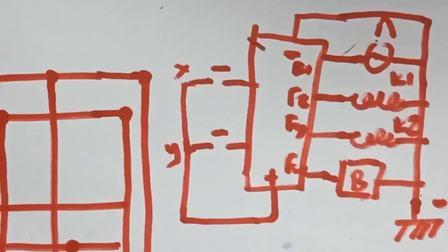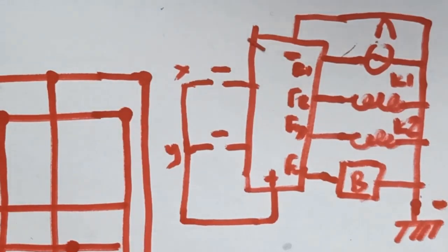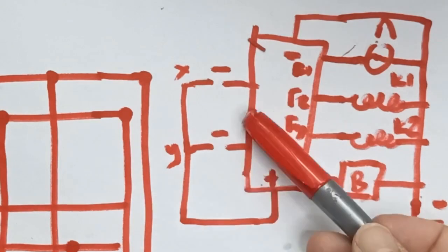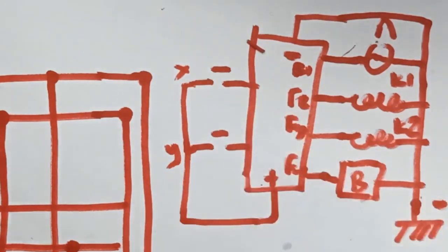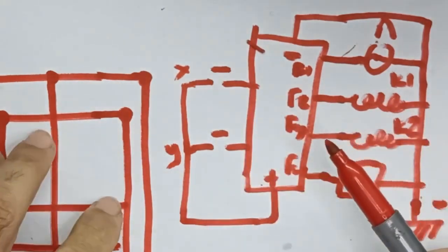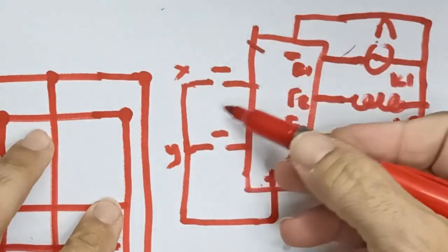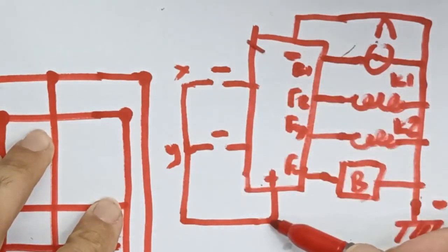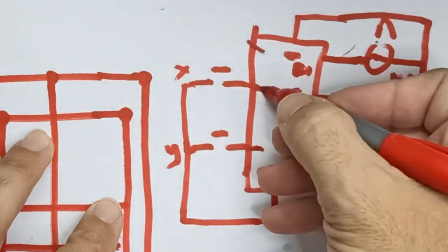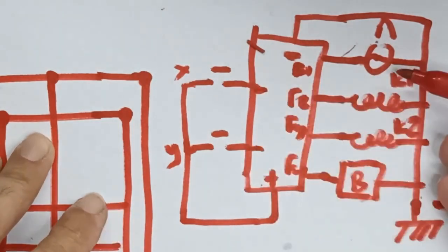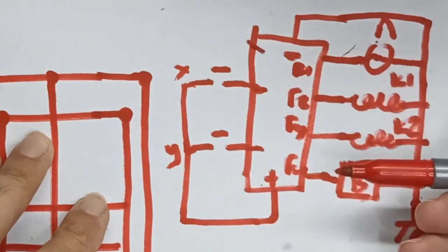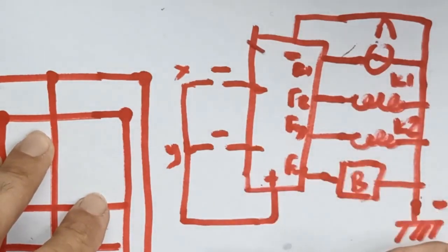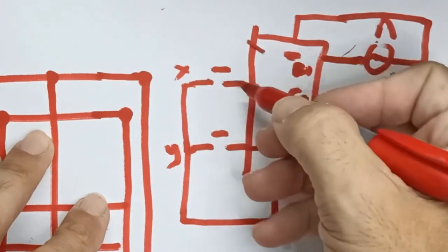Practically, we have two issues. The first problem has to do with the polarization of the input, because the gates are electronic circuits. We say digital, but in reality they are also analog. They are made from semiconductors, and they also have some internal leaks. I want to have clear inputs, that is, when we have 1 to have a pull-up, and when we have 0 to have grounding, not to be floating, because they have some internal leaks towards the inputs.